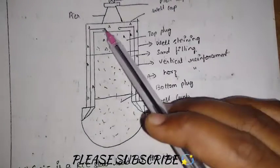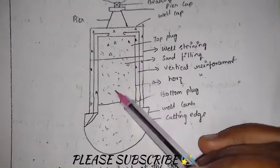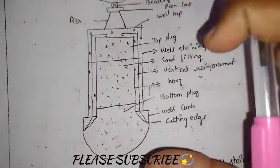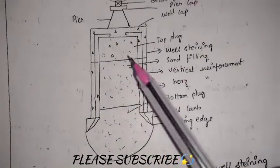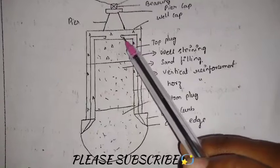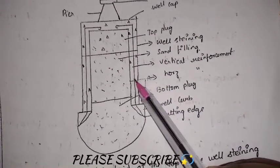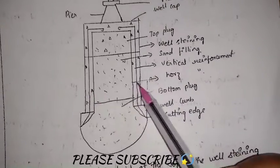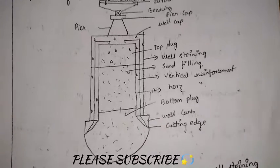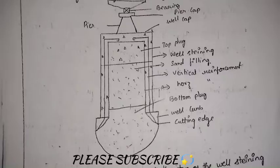And here we have a top plug and this is the bottom plug, and the middle one is the sand filling, and this is the well steining. This is the main body of the well foundation, and in between we are having the sand filling, and at the sides you can see this is the vertical reinforcement. Whatever the vertical reinforcement is there, it is here, and to this we are having horizontal reinforcements at this level, and this is a well curb having this cutting edge. I will be explaining these definitions later. So this is just a diagrammatic representation of a well foundation.